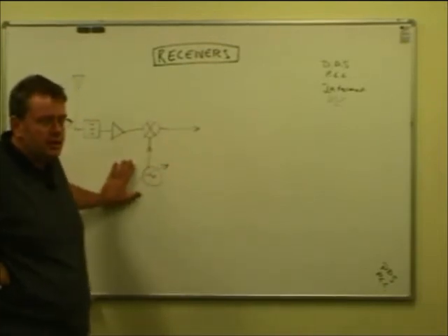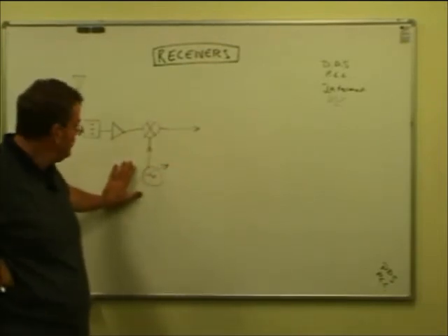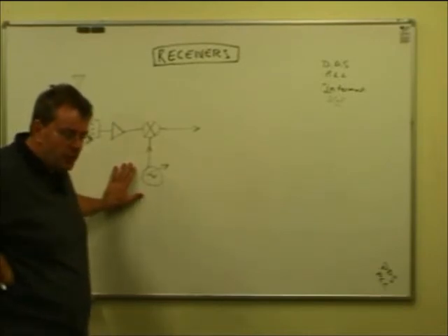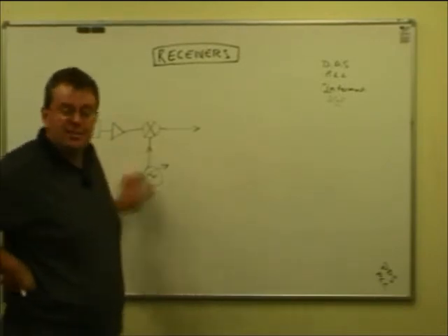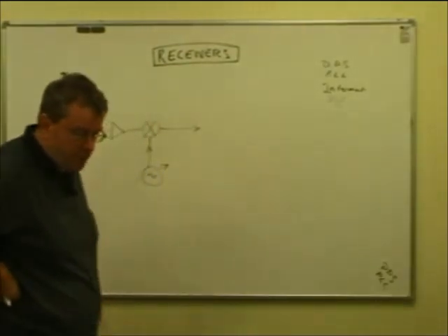But basically what was done is you had an oscillator that was running at the frequency you wanted, but it was controlled by a variable capacitance diode electrically to keep it on the right frequency.